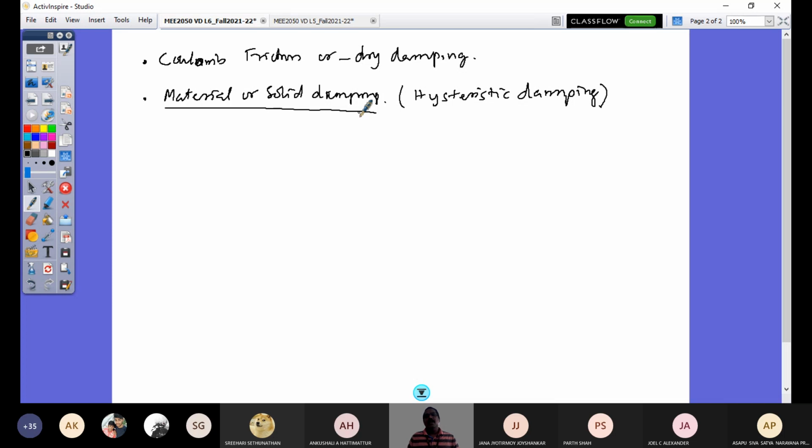And that is what is all primarily due to this solid or hysteresis damping, where the vibration about its mean position will be under loading and unloading continuously. If this is not within an elastic limit and slightly against, then there will be a loop formation that can be witnessed if you look at the stress strain diagram of that. And the mechanism of this solid damping is the relative motion between the planes forming the solid, the molecular structure.